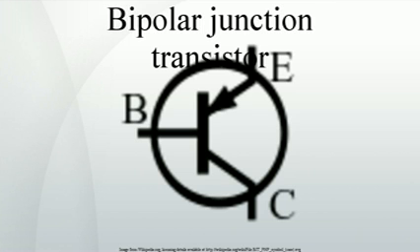In particular, the thickness of the base must be much less than the diffusion length of the electrons. The collector-base junction is reverse biased, and so little electron injection occurs from the collector to the base, but electrons that diffuse through the base towards the collector are swept into the collector by the electric field in the depletion region of the collector-base junction. The thin shared base and asymmetric collector-emitter doping is what differentiates a bipolar transistor from two separate and oppositely biased diodes connected in series.